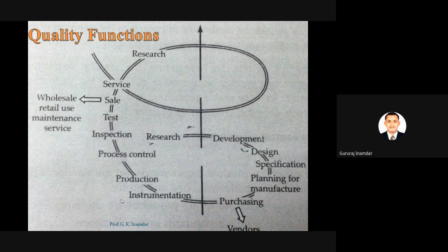Now, sampling. You might have studied sampling in first year, second year. When we were learning sampling, it did not seem useful anywhere, but you will find it in the inspection unit. Whenever your industry is a good manufacturing industry, within one day you will manufacture maybe lakhs, 10 lakh, 20 lakh of production. So is it possible to inspect each and every component? This is very difficult and very time consuming. For that purpose you have to use the sampling method.